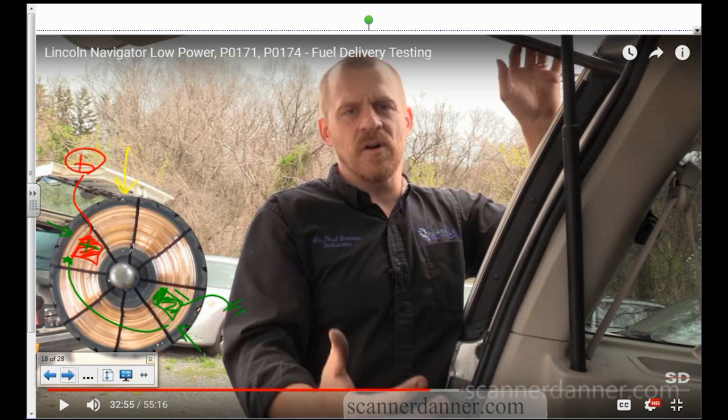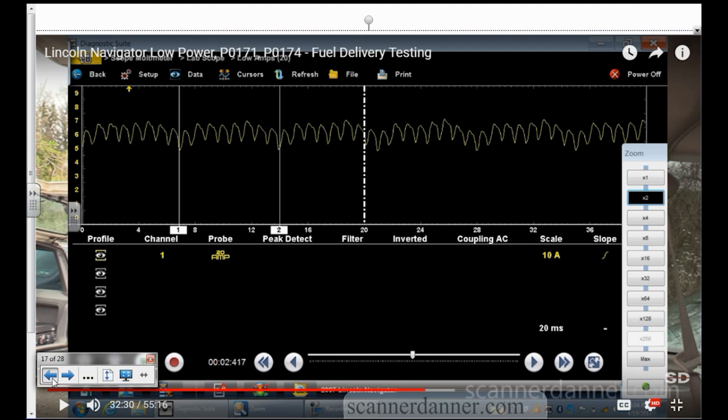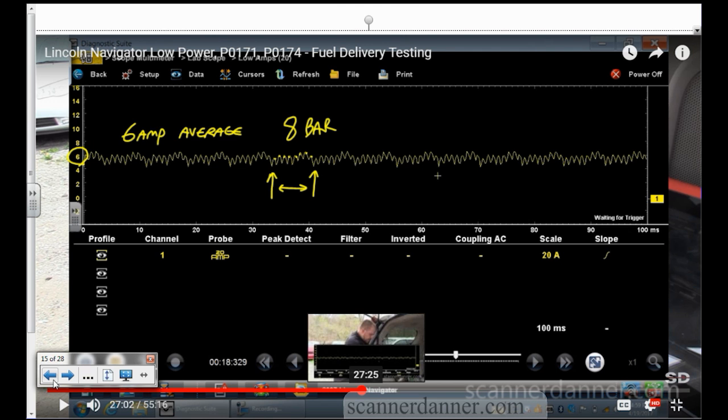So in any case, how many bars? 1, 2, 3, 4, 5, 6, 7, 8. Do you guys understand now what's making this pattern? Everyone understand the pattern? The pump's current is flowing through each of those segments. Current rises when it's on a conductor, and current drops when it's on an insulator.